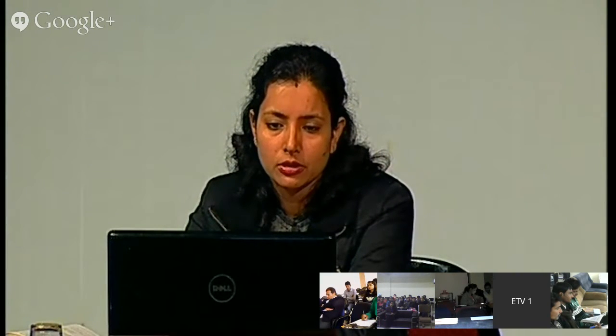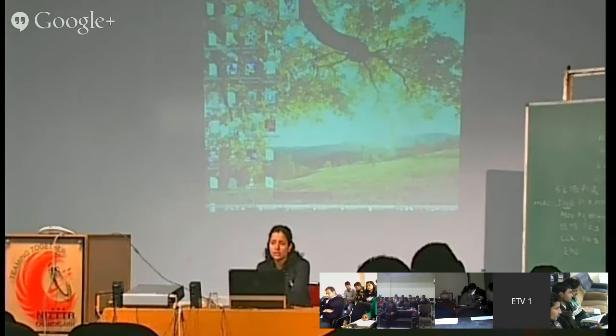So once you download the Keil compiler, you'll get this kind of icon, Keil MicroVision 3. When you go to that link, it will show you various versions. The version which you have to install is C51. You people also can download it. Download the trial version of Keil MicroVision, and in that you'll get various different versions. So download C51.